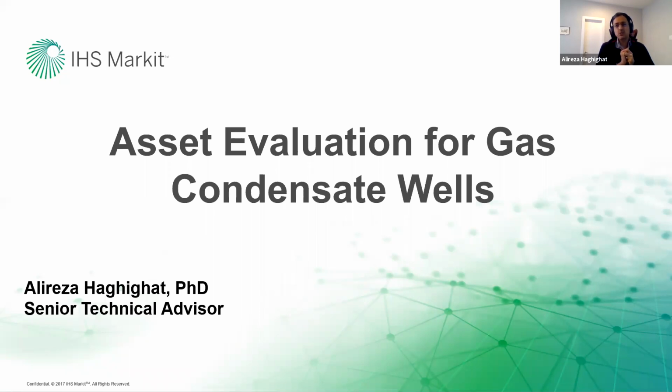You typically don't consider those data points in your decline curve analysis. You filter them out, and then you perform decline curve analysis with the points that are following the same trends. Those are some noises, those are some outliers, and typically we try not to consider them for decline curve analysis.